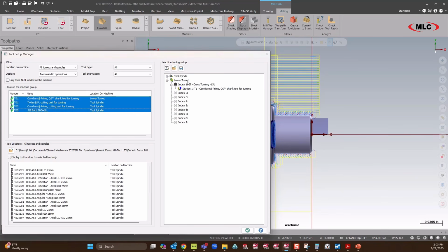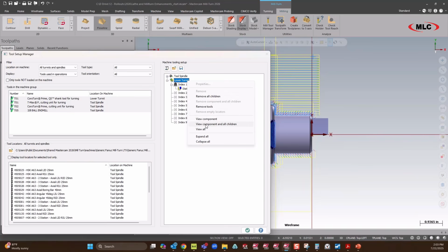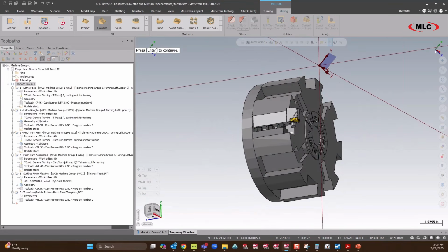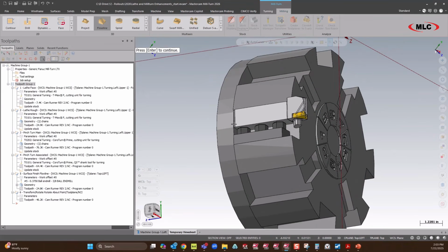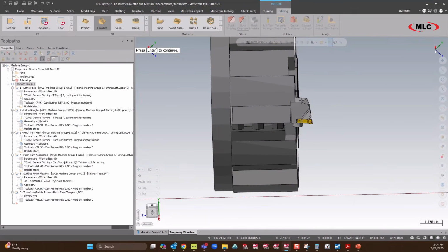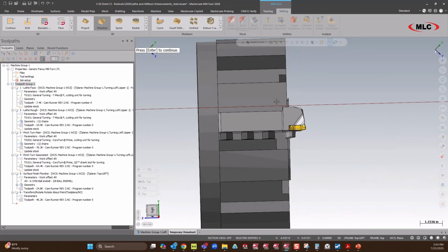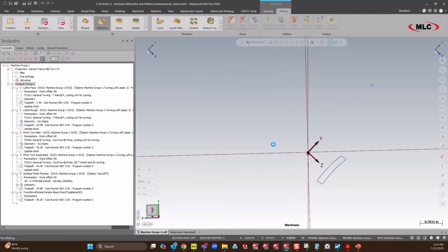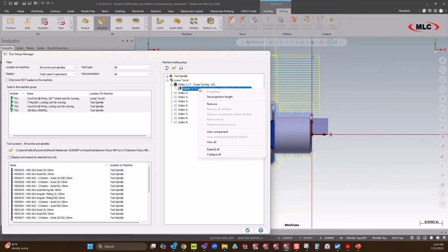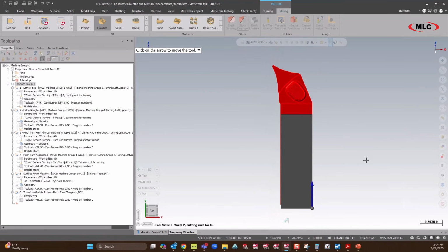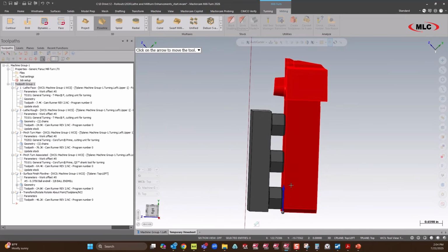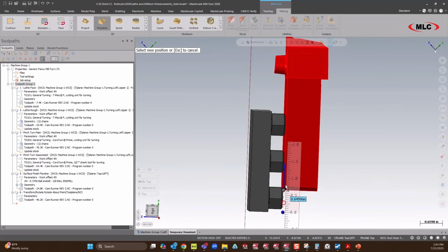And we're going to look at our lower turret real quick. And we can see it butted that tool all the way down. That may work, but it looks like we're buttoned up right there. Not a big fan of that one. Let's look at how we can extend it, and we're going to measure it off of this edge. So as before, we could set projection length. I'm going to rotate this around, and the default didn't really give us very good reference numbers.